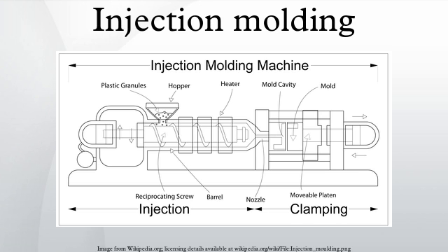When filling a new or unfamiliar mold for the first time, where shot size for that mold is unknown, a technician or tool setter may perform a trial run before a full production run. He starts with a small shot weight and fills gradually until the mold is 95 to 99% full. Once this is achieved, a small amount of holding pressure will be applied and holding time increased until gate freeze-off has occurred. Gate freeze-off time can be determined by increasing the hold time, and then weighing the part.